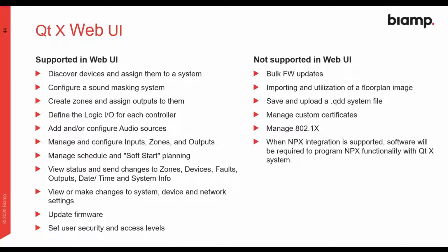You cannot use any floor plan imaging. You'll see in Qtx software that you can import a floor plan and draw over it. That's not supported in the web UI. And you cannot load a previously built system file that's done in Qtx software via the web UI. So if you build a configuration offline in Qtx software, you send it over to the person that's working on site.